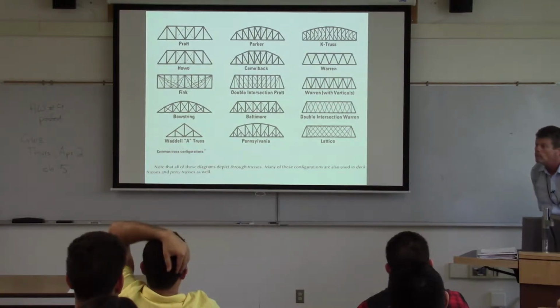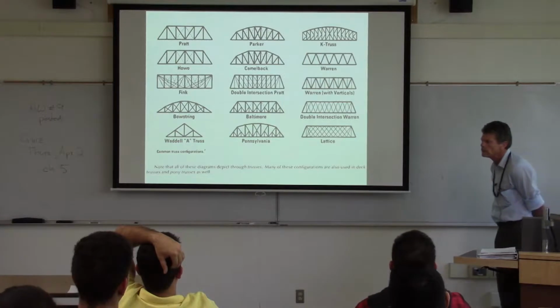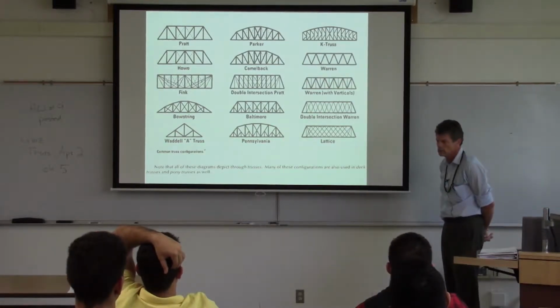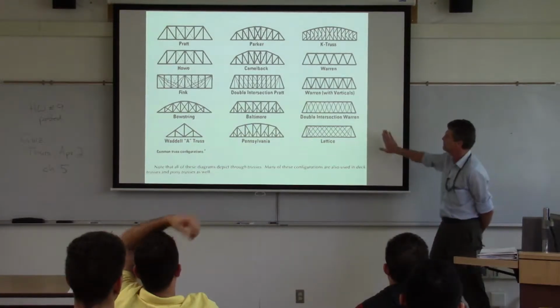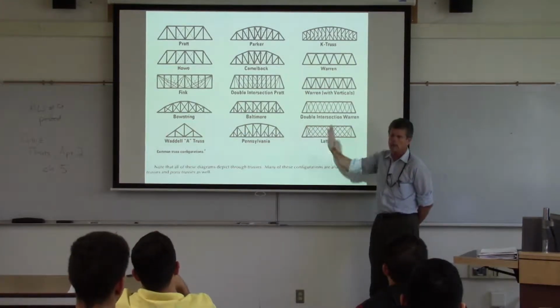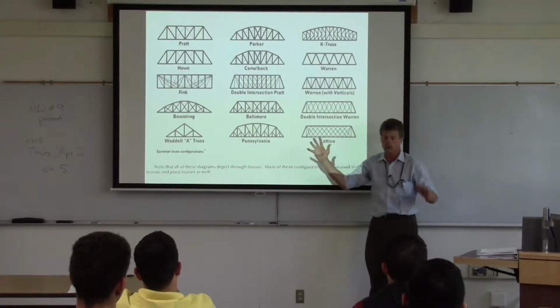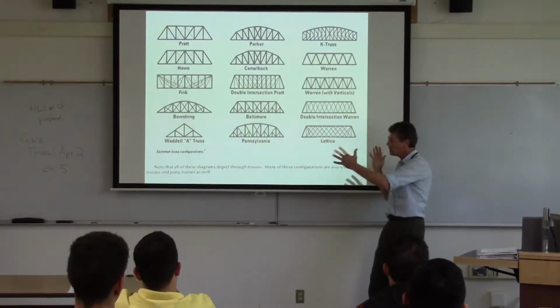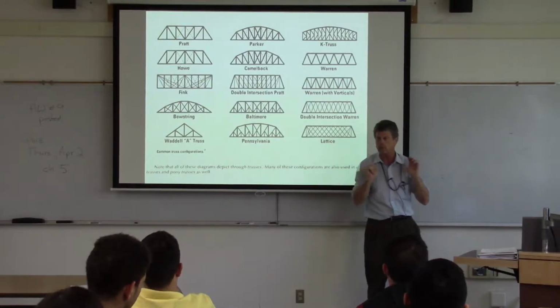So are the planes or the forces distributed the same for the different types of bridges, like whether it's an arch bridge, an under truss, over truss, or do they change for different types of bridges? Does the plane change? Yeah, I mean, this is the main load carrying plane, but if we look at it sideways, transversely, there's going to be some truss elements that are going to resist the wind. But the nice thing is that's 90 degrees off. So again, we're going to be able to look at that in terms of a plane most of the time.